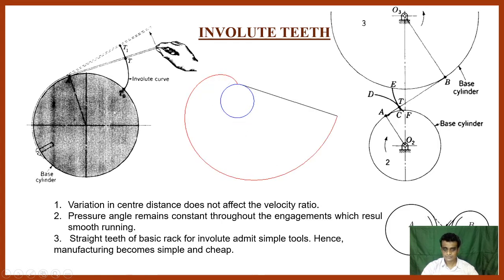Okay. The advantages of the involute profile, or how it comes: for that, we have to refer to the cross belt drive. In the cross belt drive, we consider any one point on the belt which always moves along the belt. That point B always moves along this line, which is tangent to this circle and again tangent to this circle.